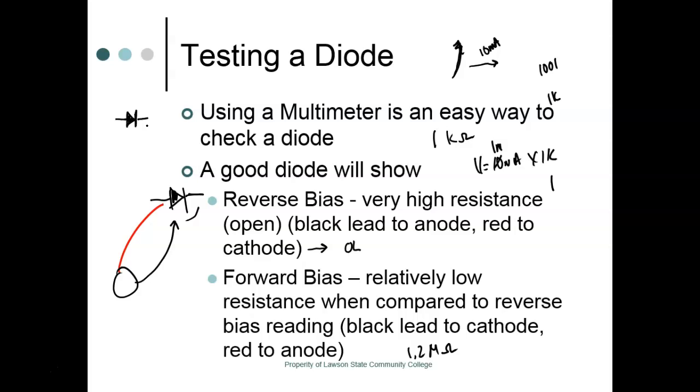So what we should see here, if I forward bias it and it's silicon, is it's going to measure approximately 700 millivolts. Because what it's doing now, instead of interpreting it as ohms, it's going to tell you what voltage was required to cause it to start conducting, right? So we still call it an ohmmeter, even though it's displaying volts.